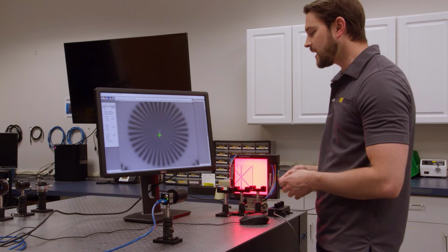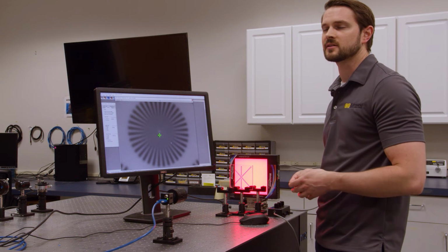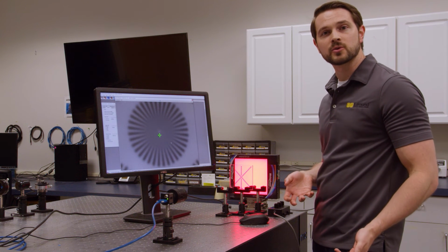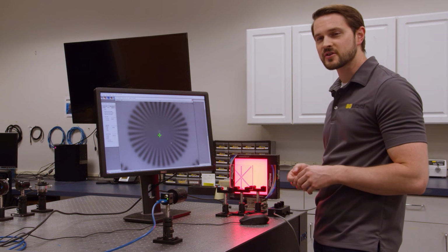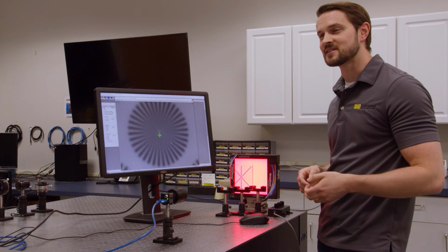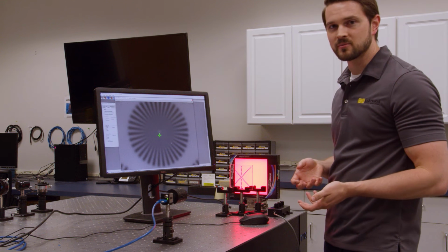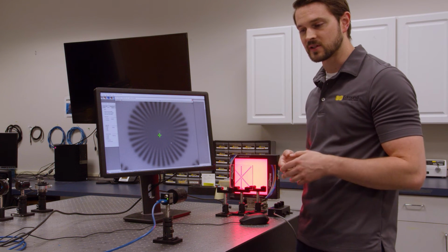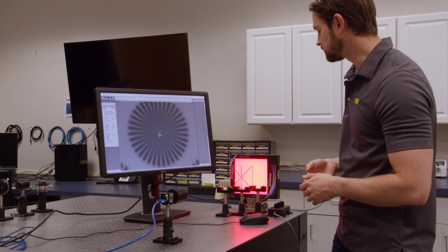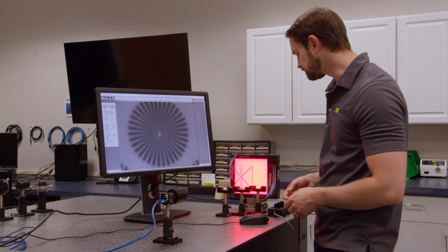So right now I'm using red, and oftentimes red is talked about as being the most common machine vision wavelength. It's a question I like to ask when I do this in front of live audiences, which is, what color is your go-to color for illumination? And for the first few years of my career, it was almost solid 100% red. And I'm actually really happy to see now that other people are starting to talk about other colors in there. But traditionally, red is used in machine vision because it was an inexpensive choice to use monochromatic illumination. And they were inexpensive LEDs when they first started coming out. But let's take a look at how the different colors actually impact our lens resolution.